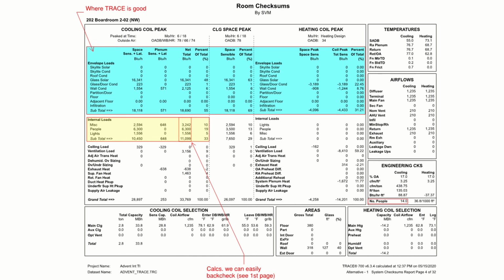Where Trace comes in really handy is when it performs envelope loads. Trace is really good at calculating loads based on weather and construction material. Those calculations require a bit more work to do by hand. So Trace is a huge help here. And that's what you see in blue.